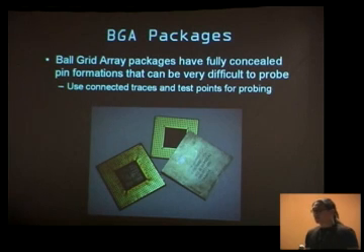It's like the kind they use in an airport, except it's got a little ability to print a film after you're done with it, and it can have a little more resolution. It can fit the focus depth and so forth. So they routinely use X-rays to inspect these packages during manufacturing, because sometimes the solder will short underneath, and you have to take a look. And so the same guys who have those assembly lines will have the X-ray and you just say, "Hey, dude, here's $20 when you put this on the line. They can take a picture for you." So.